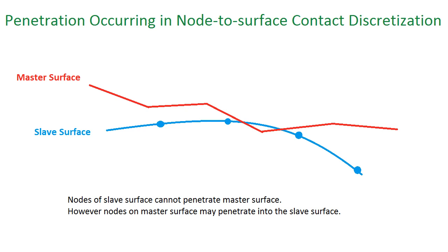Generally, surface-to-surface discretization provides more accurate stress and pressure results. However, it also involves more nodes per constraint and can therefore be more computationally expensive, although in most applications this extra cost is fairly small. Although surface-to-surface provides more accurate stresses than node-to-surface, as the mesh is refined, this discrepancy becomes less.